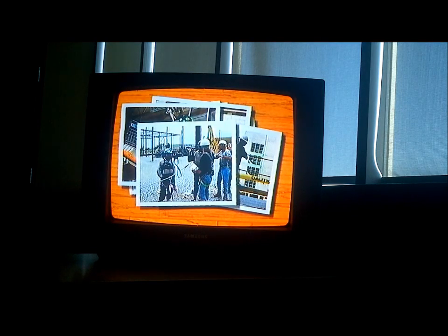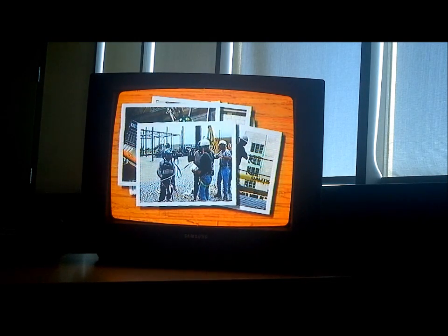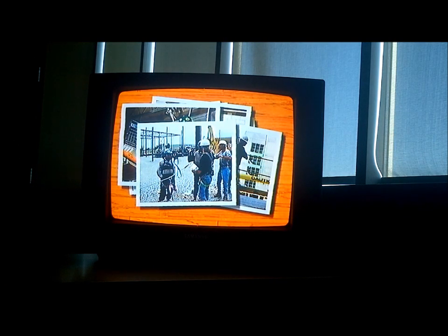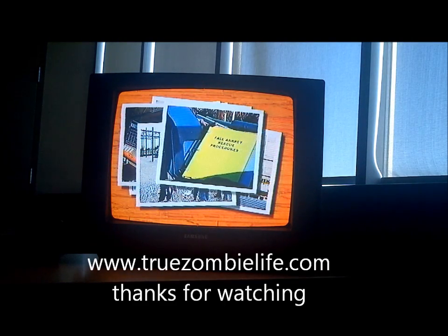Whatever the solution, you must know how to use the equipment correctly and maintain it carefully. Employers must ensure that workers are trained in fall protection and that fall hazards are controlled or eliminated. Workers must use fall protection equipment whenever it is required and report any defects or hazards. In the event of a fall, you must know your employer's written rescue plan.